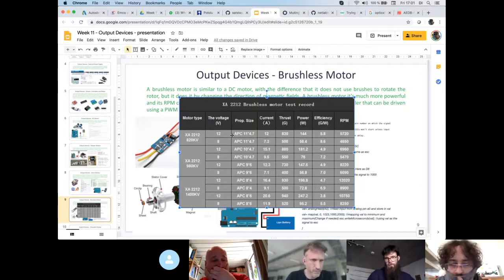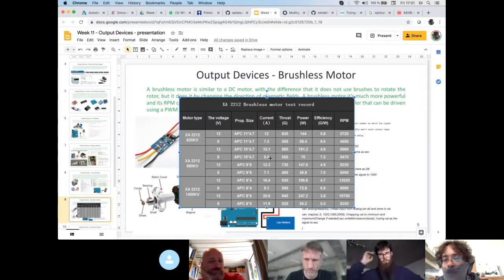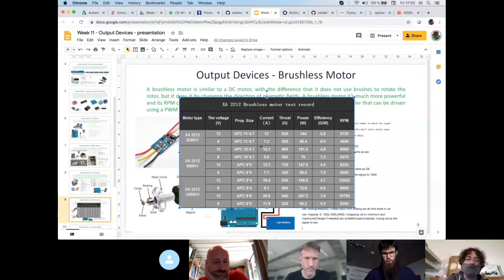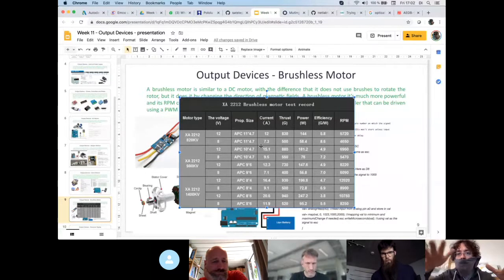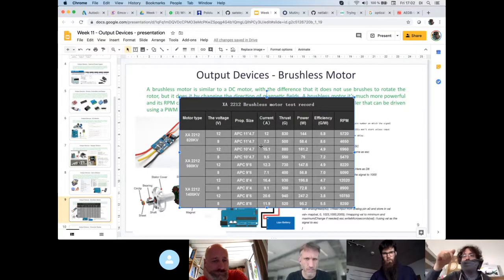So this table shows you that the manufacturer tried the motor with different propellers, because you know that according to the load, this motor can take different amounts of current. Therefore, you might need different kinds of batteries and so on. So the propeller, this is more about the drones and more about the DPV. Propellers have diameter and pitch. The diameter is just the size of the wing. The pitch is the inclination, so how much distance you cover with one full rotation inside an ideal fluid.